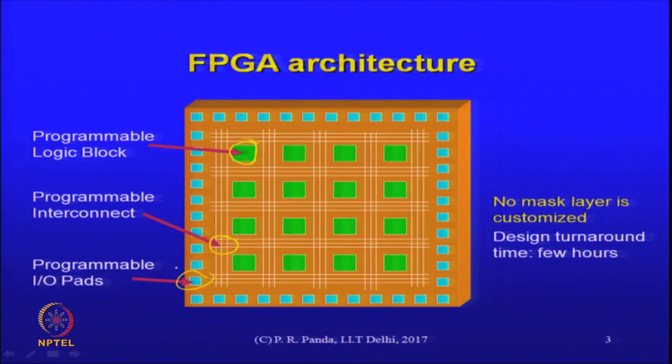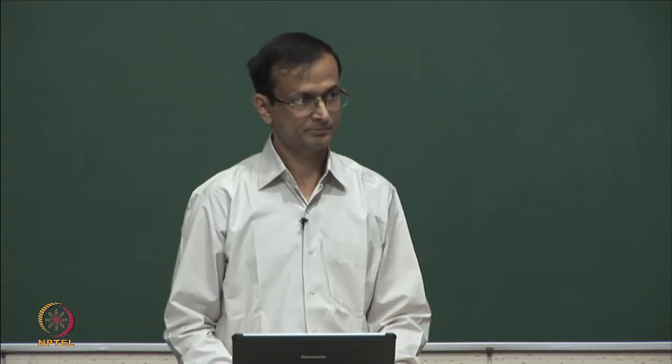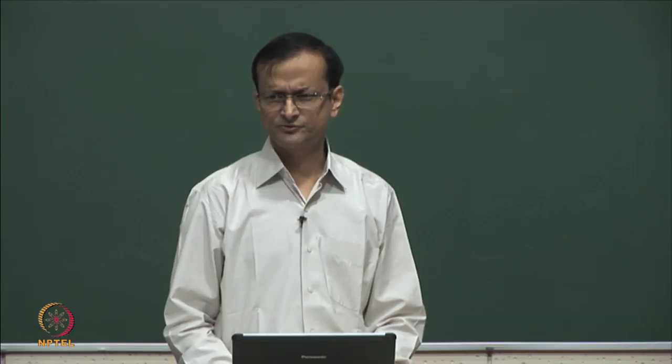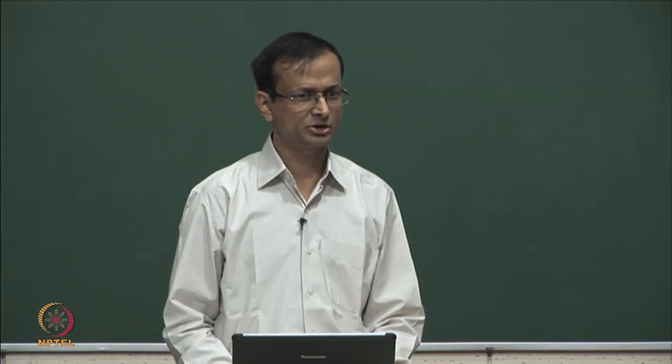Yes, it's as opposed to, for example, simulation. If you were to synthesize the same design into an FPGA just to do an emulation, the chip is not being sold as an FPGA, but the emulation is being done on the FPGA. That can be orders of magnitude faster than a simulation. FPGAs would be a much more powerful tool for testing. So the emulation is a much faster simulation. You could fix a lot of things. Functional bugs could be caught.